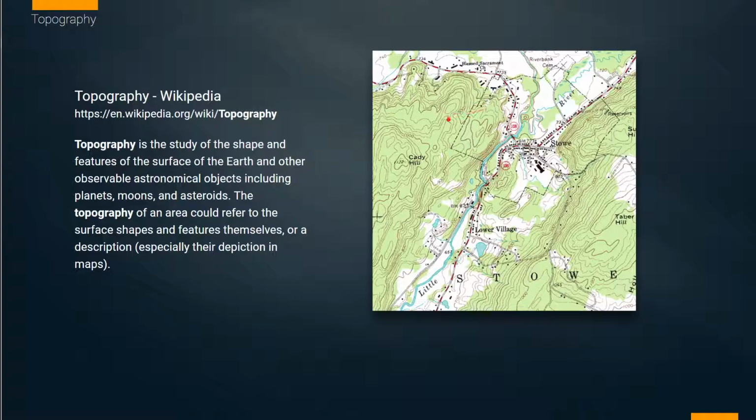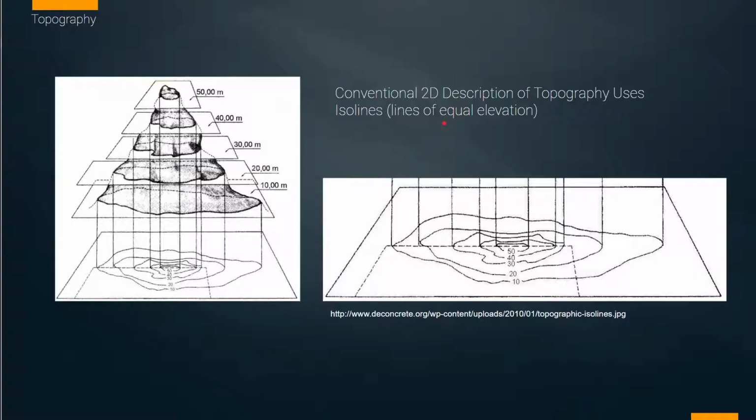These maps have been developed because they are two-dimensional representations of three-dimensional spaces. And isobars, this idea of these lines to categorize areas of equal height, is critical to the understanding of these. So we're used to working in 3D model space, and we're not really concerning ourselves many times with this idea of showing elevation in two-dimensional plan. But historically, obviously, without computers, maps needed a way to convey this idea of changes in elevation. So the concept was established of isolines, lines of equal elevation, and they're incremental, like 10, 20 feet, 30 feet. They can be any actual dimension or increment that you want. There's some established standards for that for different kinds of maps.